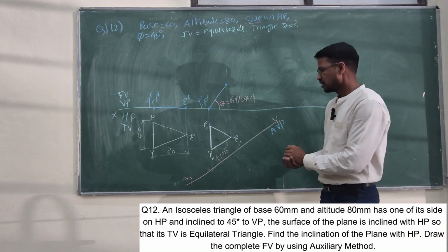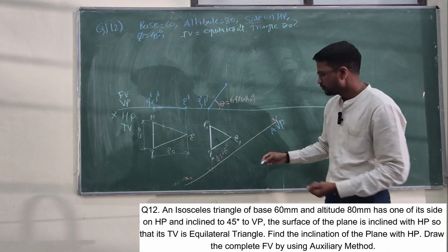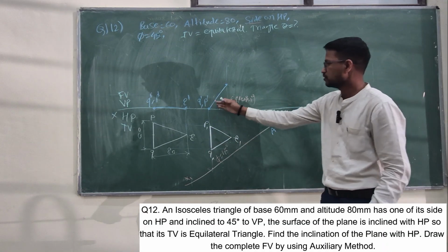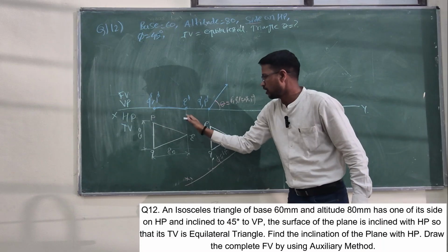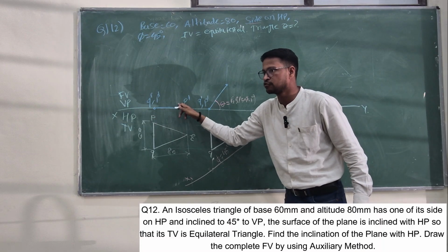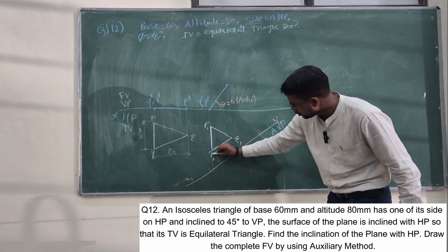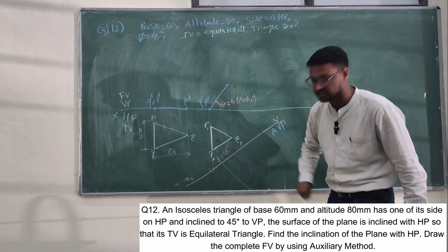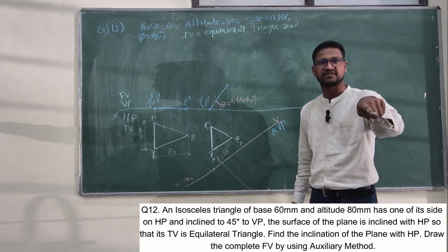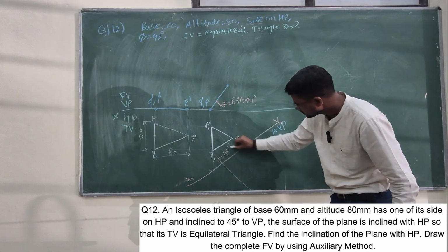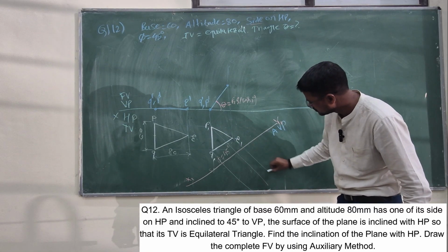Perfect. Now after completing this, each and every projector should be perpendicular. Previously, you drew the projector perpendicular to the reference line. Same thing here also. From the Q point, draw a projector perpendicular to the reference line. Which reference line? The new reference line. Which one? The X1 Y1 line. So the same thing for P also. So perpendicular. Here also same.